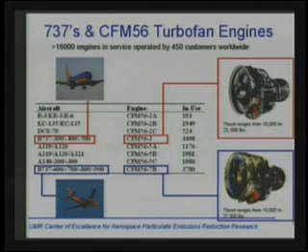And here's the engine-specific information. The GE Snecma CFM56 class of engine is the engine that powers the 737 fleets. For the 300 series aircraft, it's the CFM56-3. There are 4,498 of those engines in operation around the world. It has a thrust from 18.5 to 23.5 thousand pounds. The 700 series uses the 56-7B with a higher upper limit on the thrust. And again, some 3,780 engines are in operation around the world. So we really are focusing in on the most common engine out there in the commercial fleet.